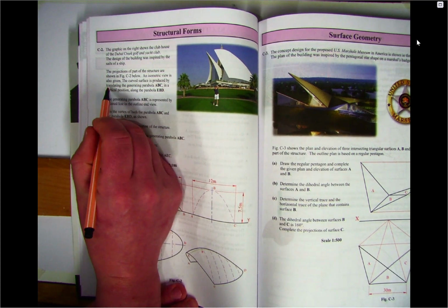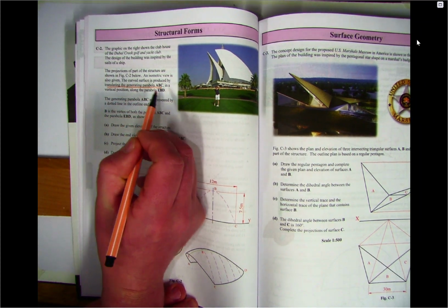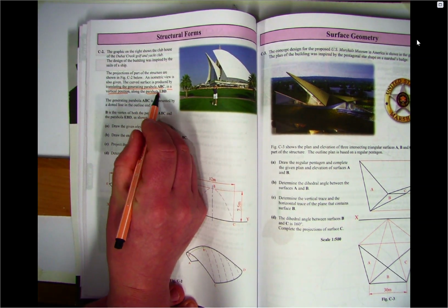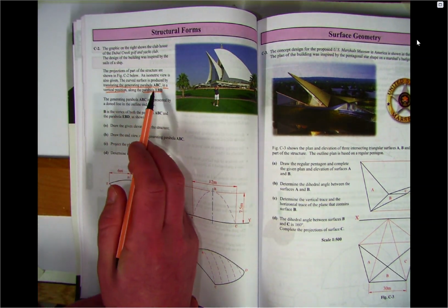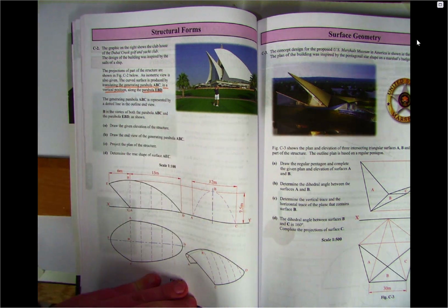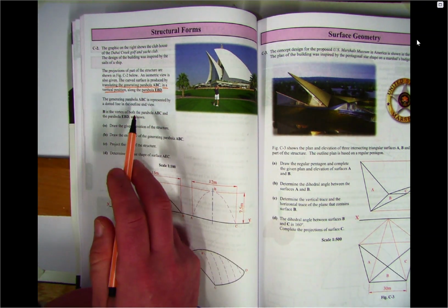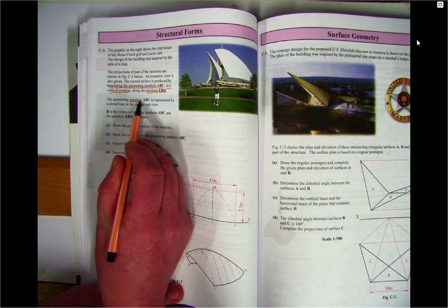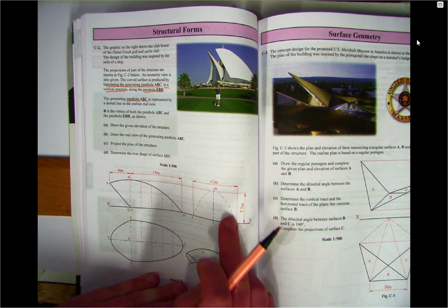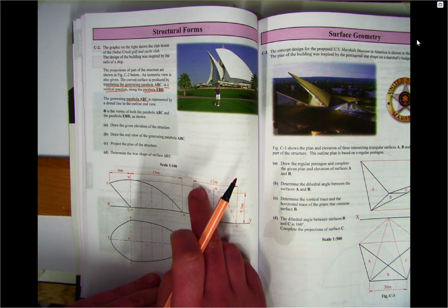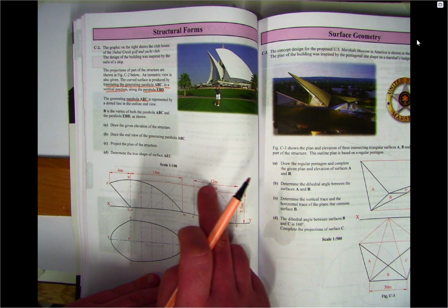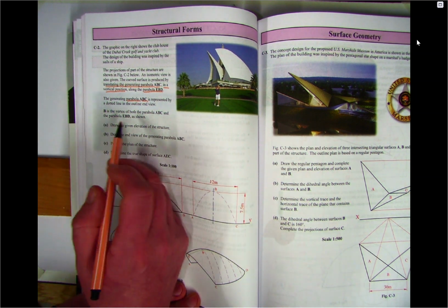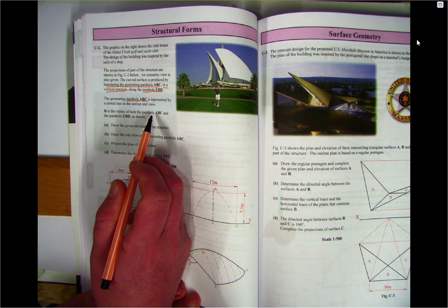It's produced by translating the generating parabola ABC in a vertical position. So in other words, the parabola is standing up along the parabola EBD. So if a parabola passes along a surface in a vertical position, then basically that's what we're talking about, shell structures. So generating parabola ABC, so again we know ABC is a parabola, is represented by the dotted line here. So this is basically, it's not exactly the end view, it's literally the parabola that was used to create this shape.